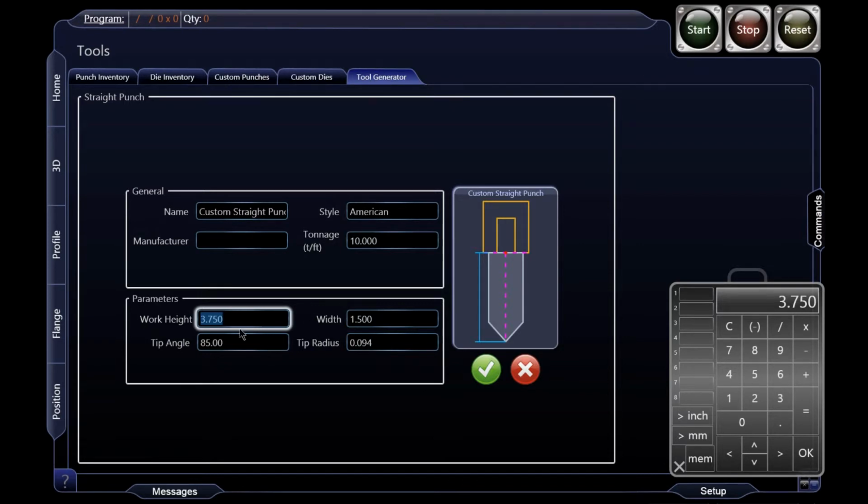We want this to be accurate. So when you're measuring your tool, reverse engineering it, ensure that you're measuring squarely with your calipers, or maybe even use a granite table with a height gauge to accurately measure it. So you want to measure within a couple thousandths, so you've got to be accurate.